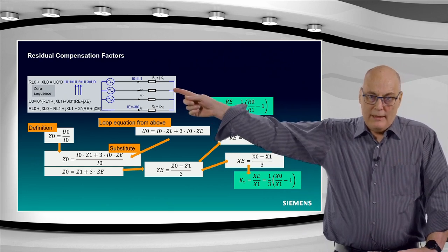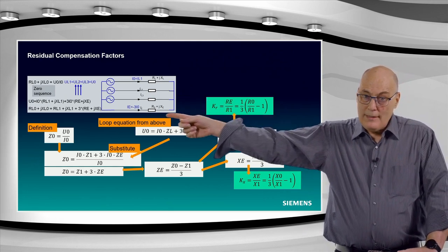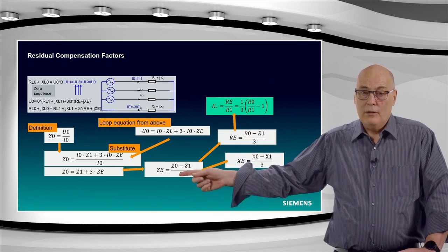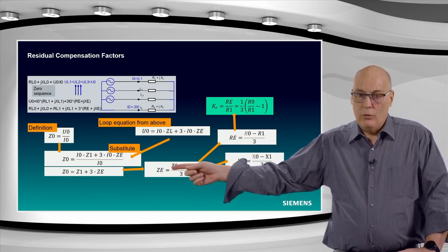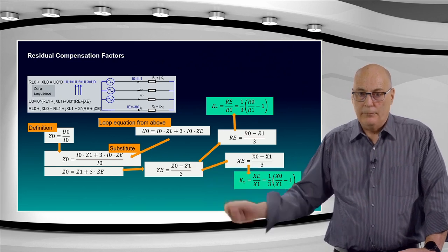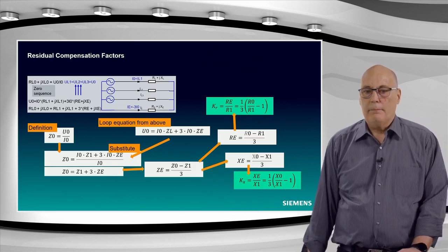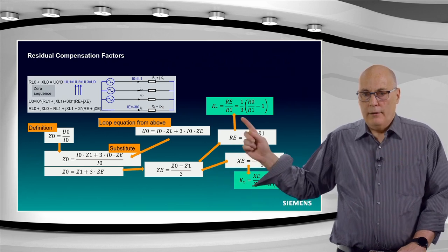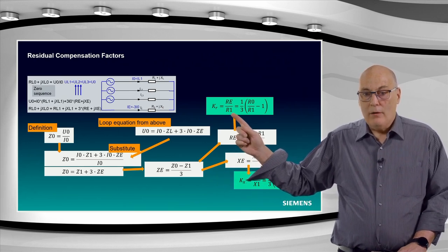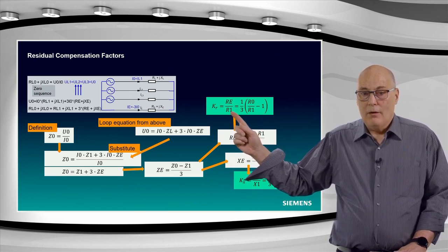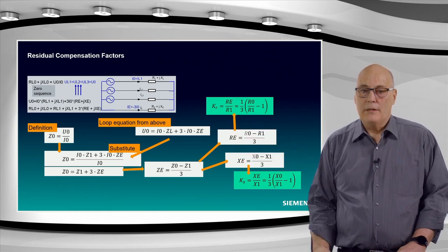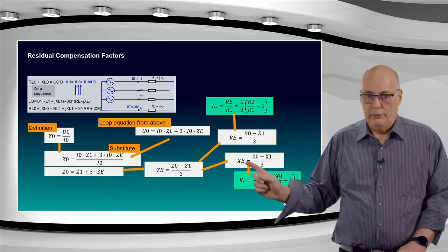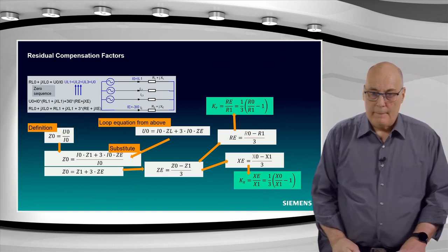and this is an important thing that I wanted to say in the diagram at the top. Remember, we said this was Z1, but this is not Z0. This is ZE down here in this diagram. Be careful: to get from Z0 to ZE, you have to use this equation, Z0 minus Z1. Right, and then from there on in, we can calculate this RE, R1. Remember, R1 is the same as RL, as such, the Kx over here. And we derive these two equations from that.